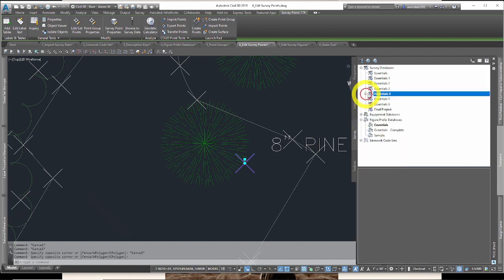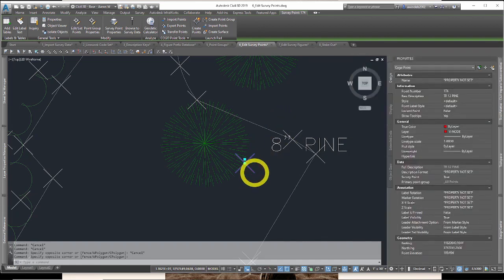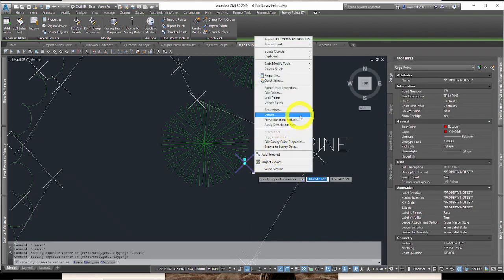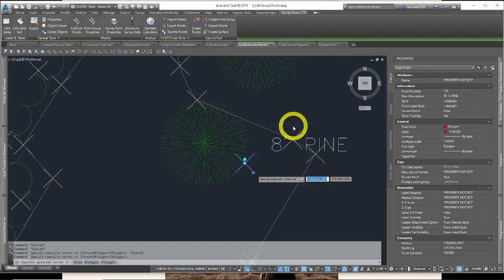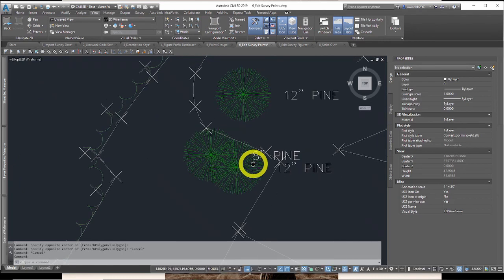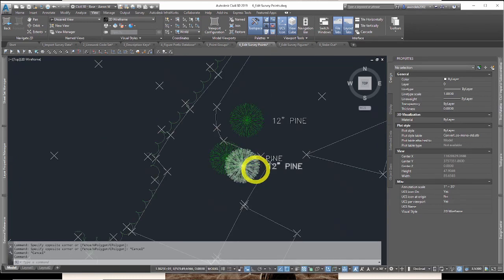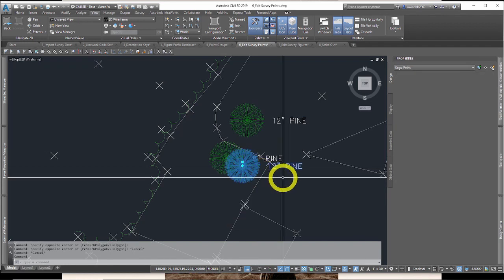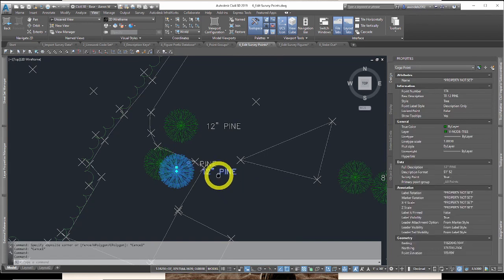So I just went between 2 different databases. I'd done one edit and I did it again, so I was bouncing between them. Let's have this still selected. Right click, and you can also pick one thing and apply description keys this way too, which will turn it into a tree, because now you have the proper coding which recognizes just TR, not TTR. So it gives it the proper point style because we corrected it in the survey database.